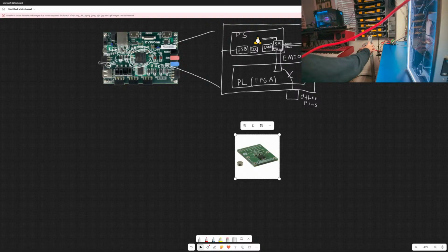When you put everything together and put the batteries on, the chassis for the quadruped, at the end of the day these might not have enough torque, so I'll have to do a gear transmission anyways to step up the torque. Anyways, I'm not there yet.